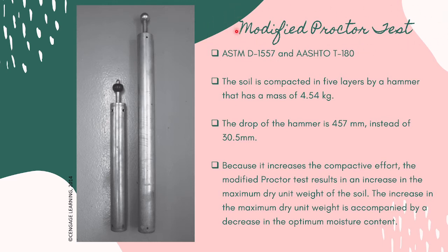The modified Proctor test can mimic the field conditions more closely, because the modified Proctor test has a heavier hammer, and then more layers of soil are compacted.